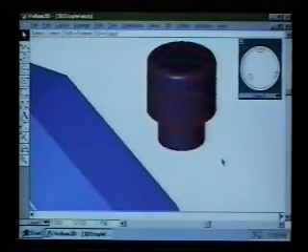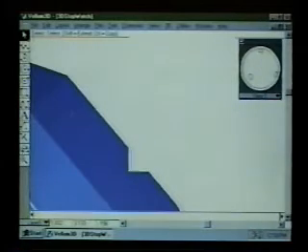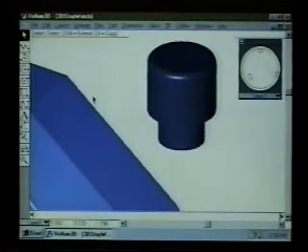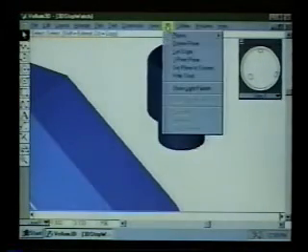So there's the button all rendered out for us. And now the next thing to do is to position it onto the work surface, which will be the edge of the clock there. To do that, we'll need to define a work plane that's going to fit that. So we'll go to 3D and say 3-point plane, because we can certainly define a new plane.